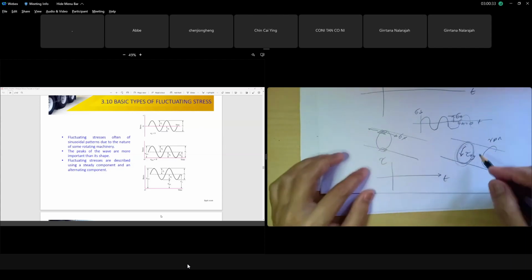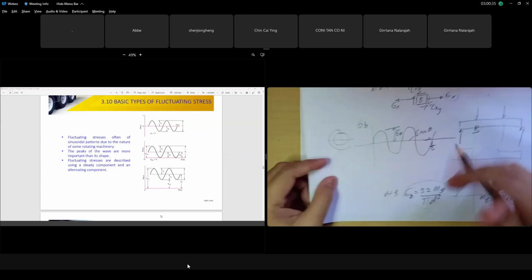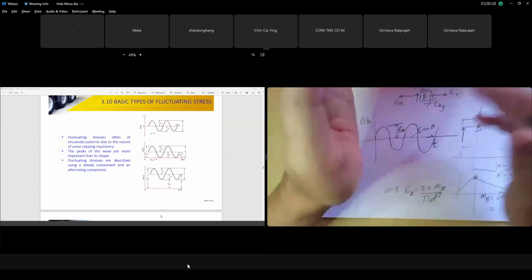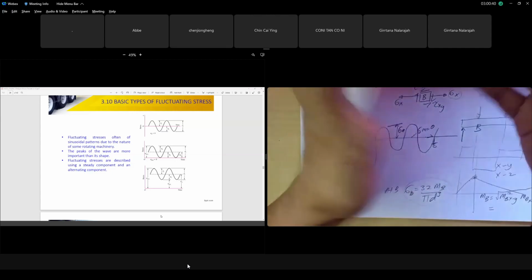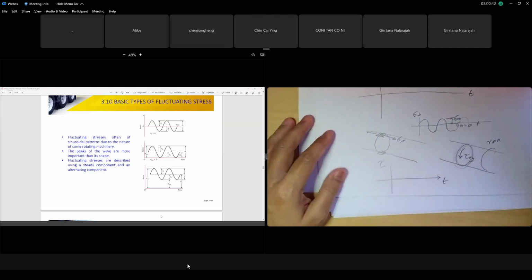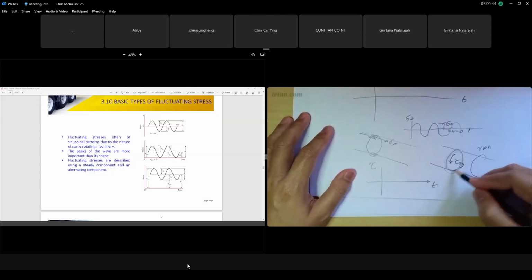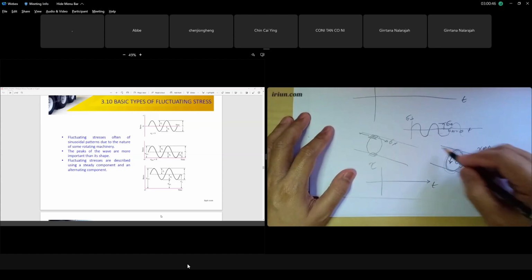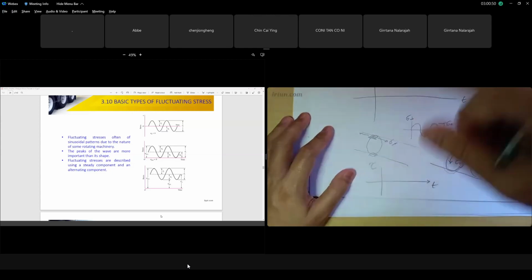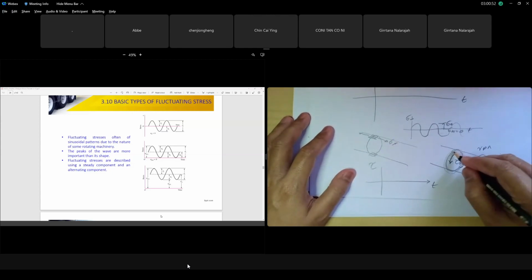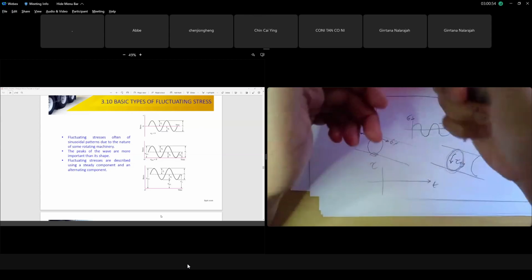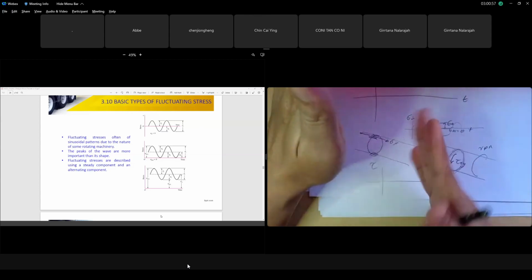Alright, also at element B, we have torsional stress, right? We always have torsion because of the pulley and gear. Between B and C, we have torsion. This is your section B's circumference, and this is your shaft, which I draw in isometric mode. The torsional stress acts along the circumference of the shaft, so your element goes like this.